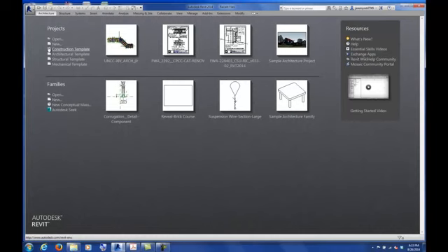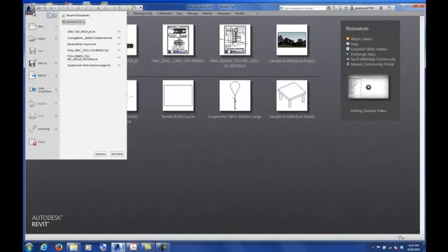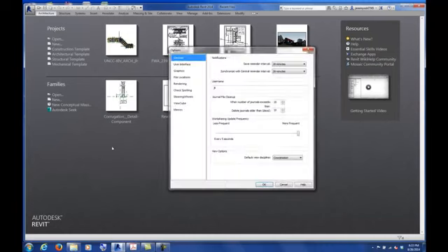And there's one thing that comes with Revit that's actually kind of nice, and you might want to utilize it when you start using Revit on your own computer, such as what I'm showing you here. Under the Applications menu, if you go to Options, there's this option to save file locations, basically kind of like a shortcut on your desktop, but a shortcut that we can save within Revit that could point us to specific locations on our hard drive or wherever you might be working on a network.